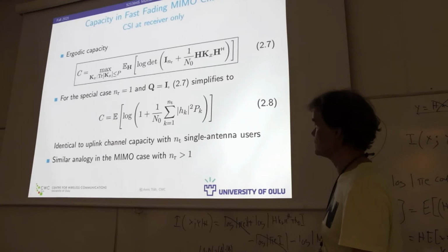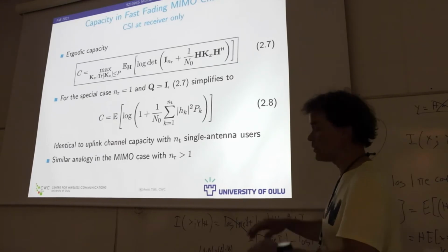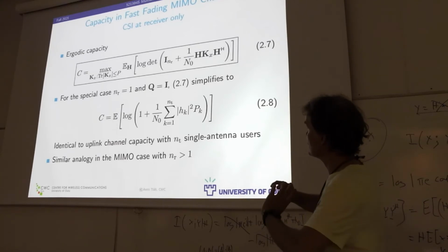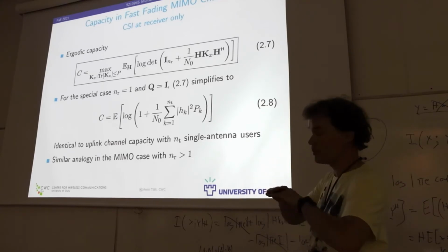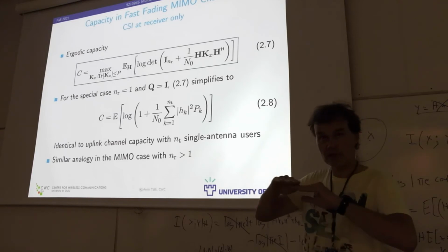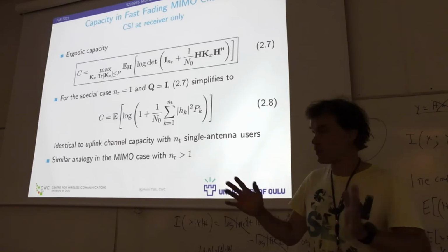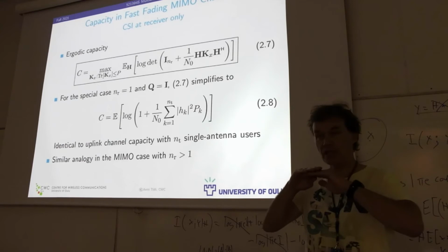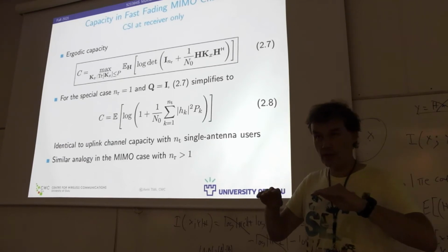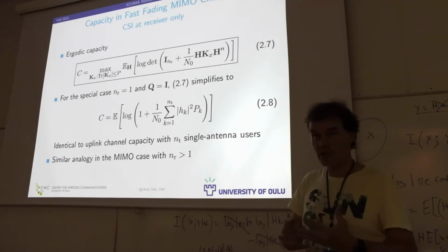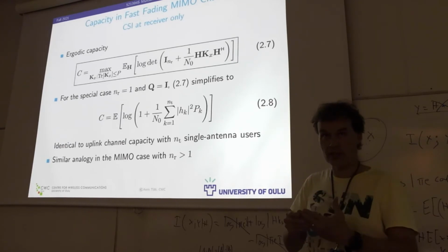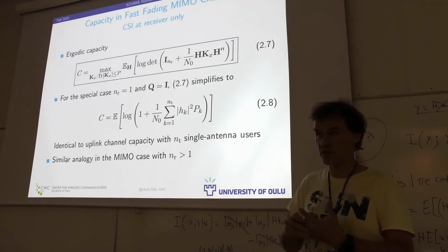So basically, if you have an uncorrelated fading process, for example, and you have an average power constraint, then you should have a strategy which is optimized over both space and time, possibly over frequencies. Of course, that's often not practical, and often you have the instantaneous power constraint. So in my setup, this optimization is carried out for each channel realization separately, given this power constraint.